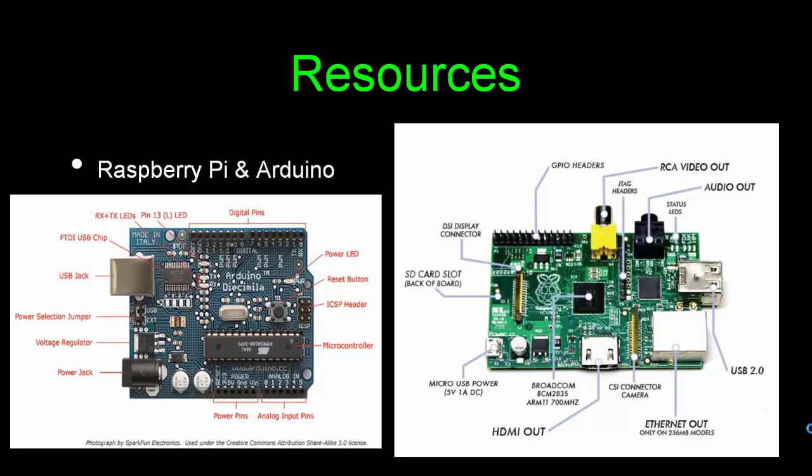The programs can be written directly on these devices to go ahead and send us the data flow as we need it, or we can do direct communications. But for our purposes, it might be better, and we'll talk about it, but it might be better for the device to collect the information and to do data dumps periodically through the day, and maybe just once at night or something like that. But also, you can control these remotely because these general purpose IOs are both digital input and output, and a shield adapter that goes on the top that we also have 3 of those for A to D conversion. And A to D will be important when we do the general cooling and main coil cooling, because we're going to be monitoring an analog signal there.